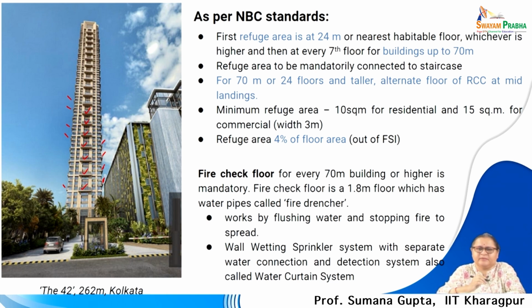So, by definition it is coming as an open terrace and not coming under the FAR, but every floor by this way has received a refuge balcony, and because each of the floors are very private, they need not mix up with the other building inmates, like in a common refuge area above 5 floors where people can come and get accumulated. So, here independently you are standing in a refuge area and waiting for your help or your rescue.